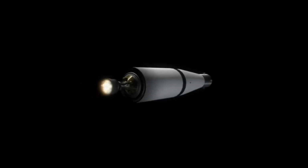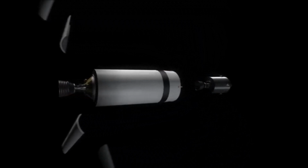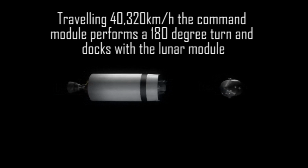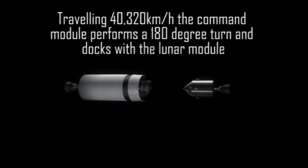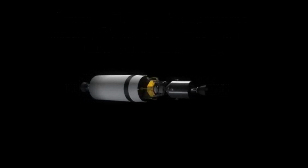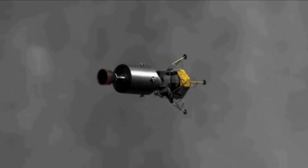After the S-IVB fired its engine to put Apollo 11 on its trajectory to the Moon, it was followed by a separation by the CSM, which would have had to use its RCS thrusters to move away from the S-IVB. The CSM would then have to turn 180 degrees to move towards the S-IVB to dock with the LM to extract it. The CSM, now docked with the LM, would then have needed to turn 180 degrees back to its original position for its continued trajectory towards the Moon initiated by the S-IVB.